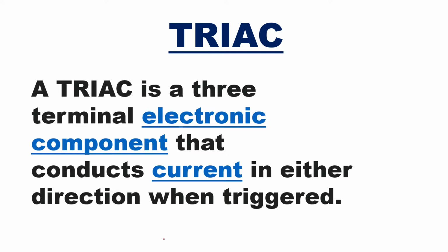Here MT1 and MT2 are main terminal 1 and main terminal 2, and either one can be positive and either one can be negative. Similarly, the gate pulse we give can be positive or negative, and it can conduct in both directions. It is a bidirectional device.